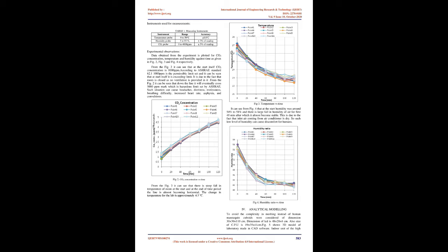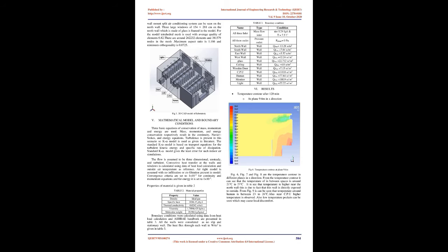2 Methodology. A. Heat load calculation. Heat load calculation is done first to evaluate the required heat load for the laboratory. Heat load calculations were done based on the following considerations. Location, Mumbai. Building area, 939 square foot. DBT, 34.1 degrees Celsius. Latitude, 19.12 degrees north. Longitude, 72.85 degrees east. Mean daily temp, 11.8 degrees Celsius. U overall values of the materials, from ASHRAE Standard Data Book.